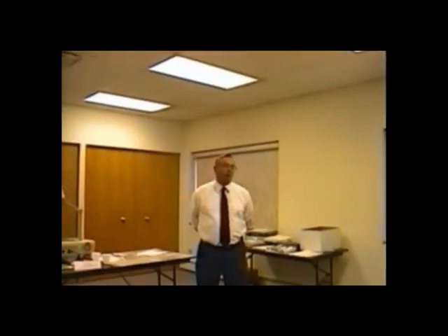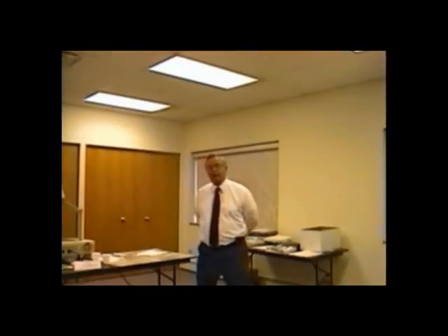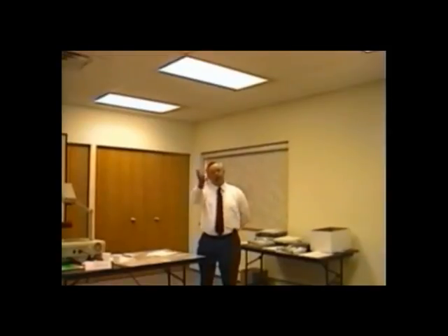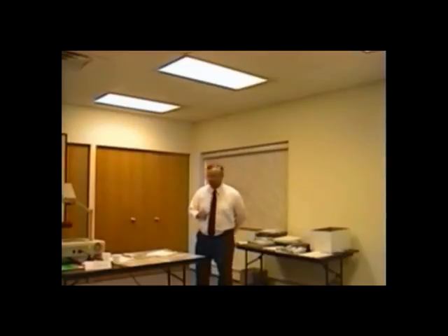Now again, different people, different methods, and different opinions. In this class, we're going to be talking about critical charges plus or minus 2 ounces. So if in fact the system took 50 ounces of refrigerant as being a residential AC, if it actually took 50 ounces, if you charged it from 48 ounces up to 52 ounces, you would be accurately charged. And that system would last forever. As long as you did an annual PM check and cleaned the condenser and had the proper voltage all the time, that system is designed to last 20 years, but I got to tell you, if it's accurately charged and maintained, it'll last forever, okay?